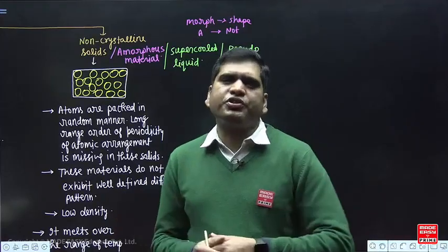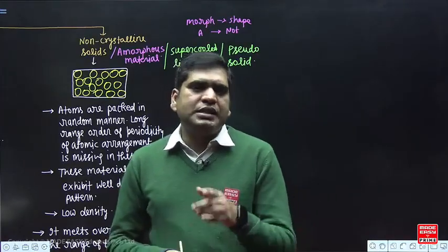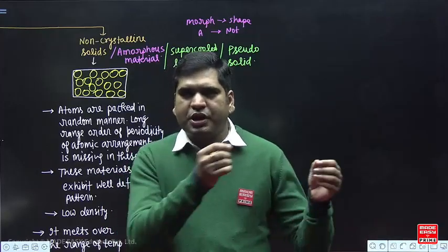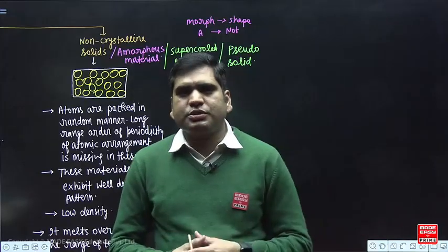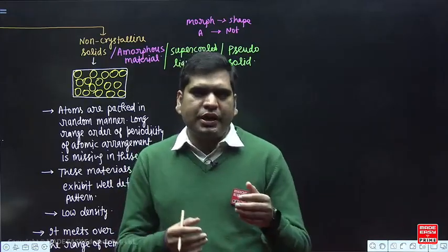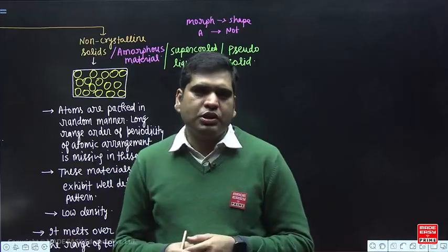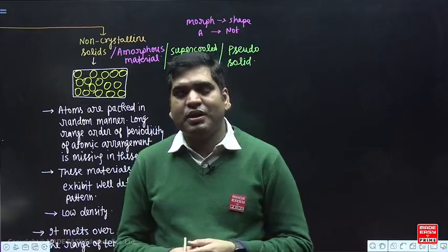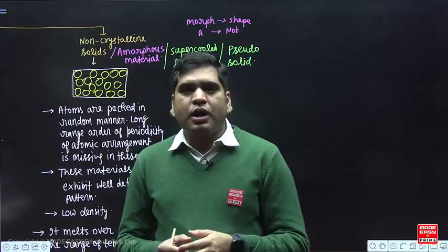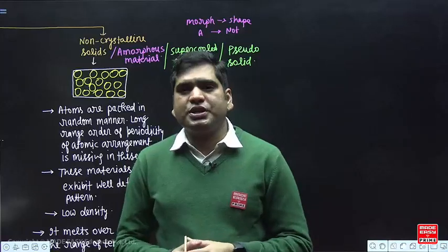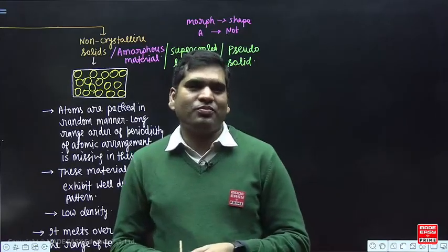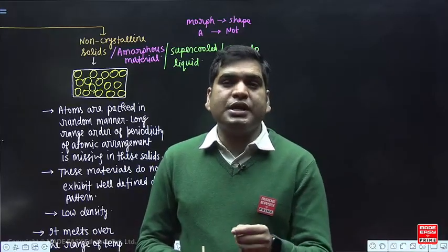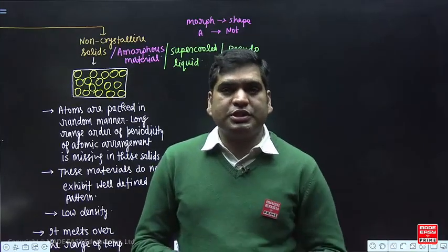Now he performs operations on this material and then he tries to cool it again. So he keeps some water and he puts that metal piece into that water. When he is putting it into water, actually he is lowering the temperature. So again he wants to make a crystal from that molten state. This process of again getting a crystalline state is known as recrystallization. And during the recrystallization process, the rate of cooling decides the transformation of the material.